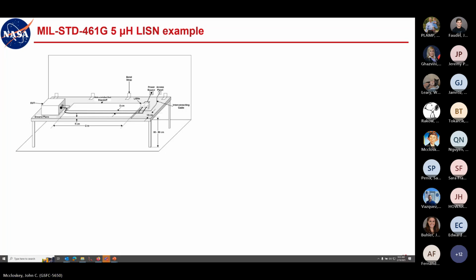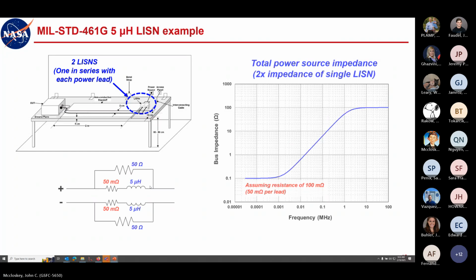Okay, so one thing to note here is, if you're going to use these LISNs, one thing I forgot to mention, I did talk about this last week in the overview section. Going back to, yeah, here we go. The traditional way I showed this impedance model here, this type of schematic really is a line impedance simulation network, which is one of the two definitions of LISN.